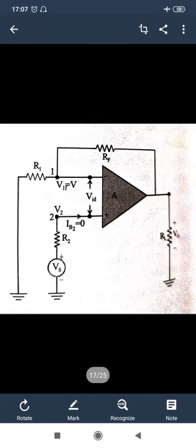So in this diagram where we use the non-inverting terminal, we put the source at the non-inverting terminal and the inverting terminal is grounded, and we provide the feedback in terms of voltage output in series with the input source. That is the voltage series example of non-inverting amplifier, operational amplifier with feedback.